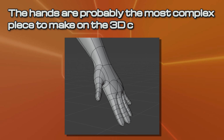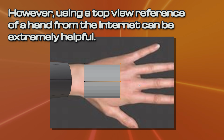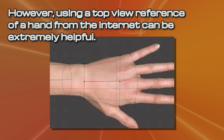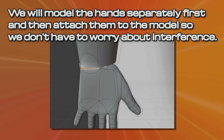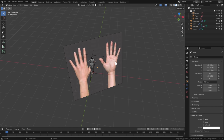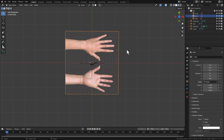The hand is probably one of the most complex pieces to make. Being notoriously bad at drawing hands, I found that it's really helpful here to find a top view reference of a hand on the internet and then model around it. We will actually model the hand separately and then attach it once we're happy with it. Find a hand reference as mentioned before and import it into the Blender scene. You can use the one I used, the link's in the description.